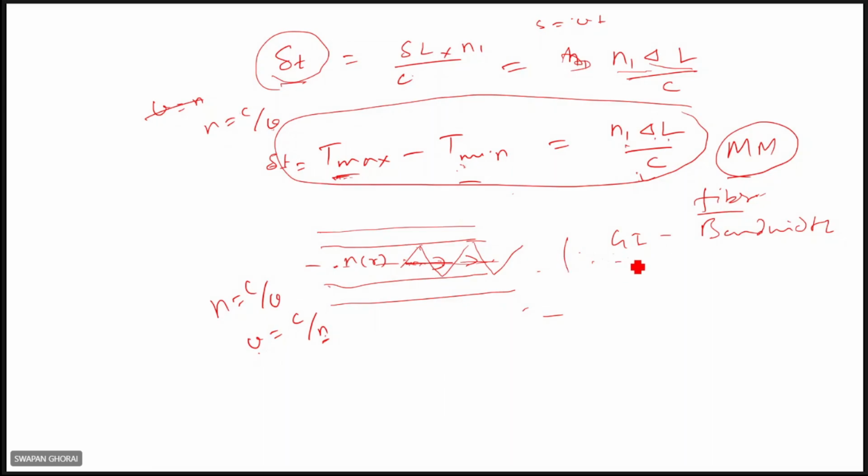That's why generally for metropolitan cities, GI fiber is used. Generally, multimode fibers are there. SI multimode fiber is avoided because its bandwidth is small compared to GI fibers. SM fiber also can be used, but there are some other constraints, like you need only laser sources, otherwise power launching problems will be there. So many problems are there in SM fiber. Advantages are there, disadvantages are also there.